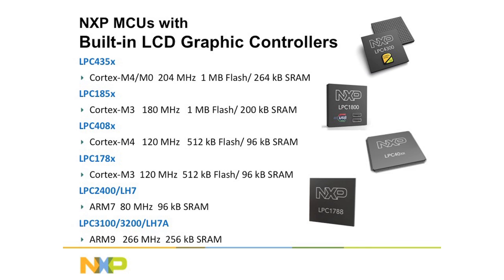So think of the Cortex M3 as the replacement for the ARM7. I'm kind of oversimplifying, but that's basically the way to think about it. So if you're moving forward, you want to look at the Cortex M3 for a nice solid microcontroller. The Cortex M0 is a cost-reduced and power-reduced version of the M3. Code compatible, but low power, low cost, you'd look at the M0 or now the M0 Plus.